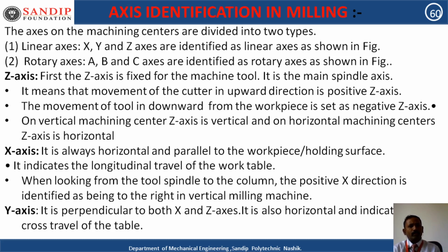So how is the 12 degrees of freedom arrived at? In the XYZ axes for the 3D components, from the coordinate point of view, there is plus and minus. Similarly, forward direction is positive and backward direction is considered negative. Similarly, the six directions, X, Y, Z as plus and X, Y, Z as negative, make six, and for rotary axes A, B, C are used, with one clockwise and one anti-clockwise. So similarly this six, the total is 12 degrees of freedom.